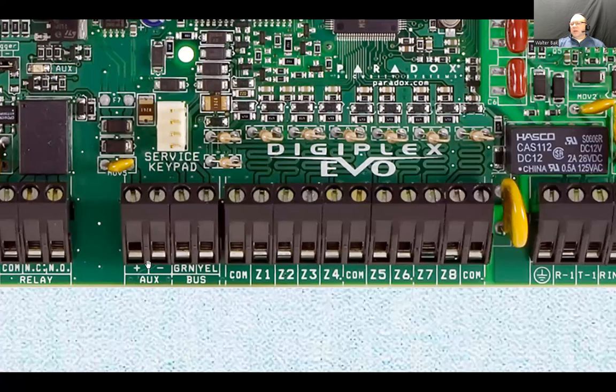Now, mind you, you should consult the manual of this system to see what the ampacity is, how much load it can handle, and what the maximum current draw is. You can only add so many motion sensors and keypads and other smart devices before the system says, that's as much as I can handle, I'm not going to work if you keep loading me like that. So if there are more devices than you can connect, you can get power expansion boards and install them beside this unit, and it gets its own separate power and separate backup battery and whatnot.